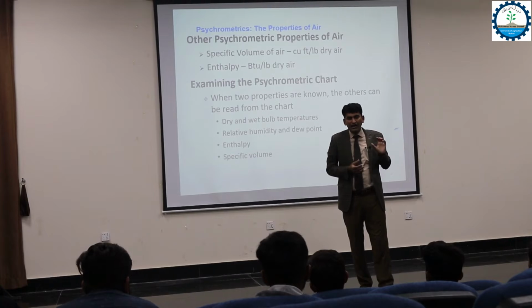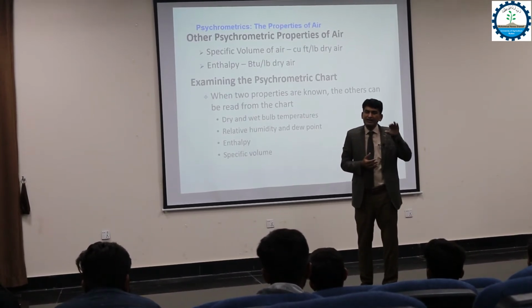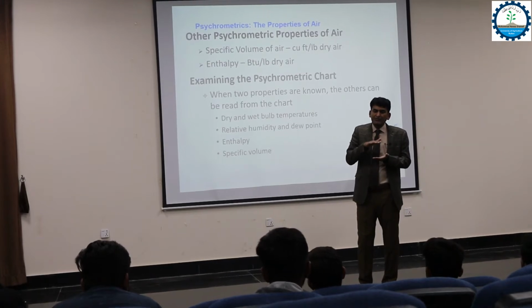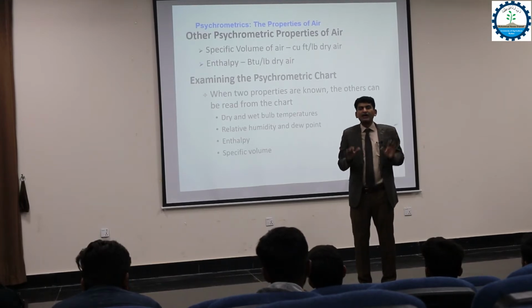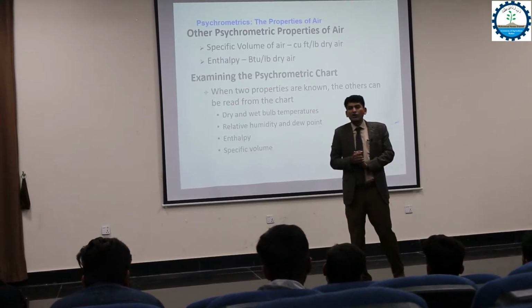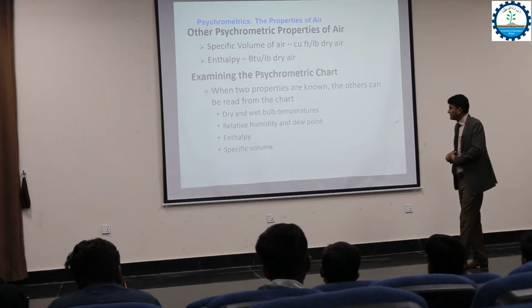So with any addition of moisture, all the vapors will condense after the 100% saturation line, or 100% relative humidity. There is no capacity in the air to sustain the moisture. So that point will be the dew point in those conditions. Okay,